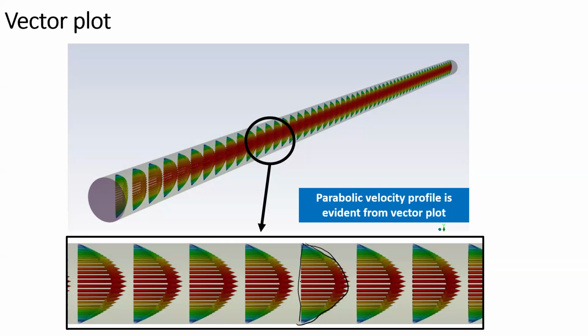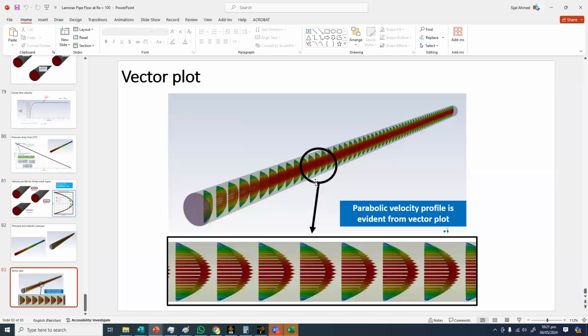So this is a very simple problem, but it will give you a lot of details about the working in CFD and how to convert the problem from the statement to the geometry, meshing, boundary conditions and fluid properties. And then finally, how to compare our results and validate our CFD simulation from known data. Known data can be an analytical solution. It can be some good CFD. It can also be some experimental data. So for example, here,